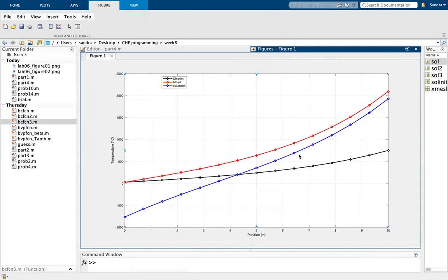The black one is what we saw earlier, the first part of the question, that is Dirichlet boundary condition. Now, if you have mixed boundary condition, which means you will have a function value and a gradient value given to us, that is the red one. You can confirm the function value here. See here the function, here it is 25 degrees Celsius, similar to the first black curve. But here you have the gradient to be a different value. If you want, you can just calculate the gradient here numerically and confirm if it is right.